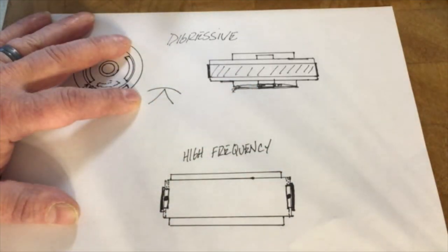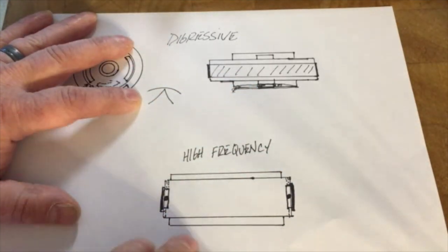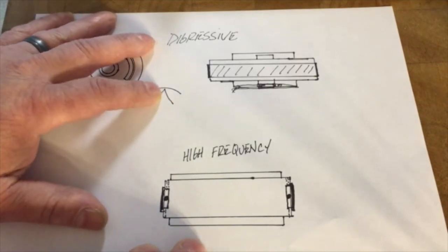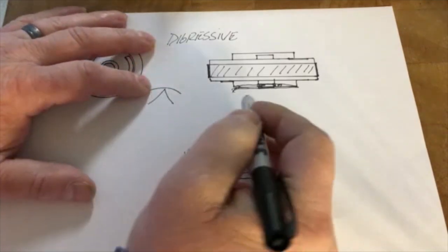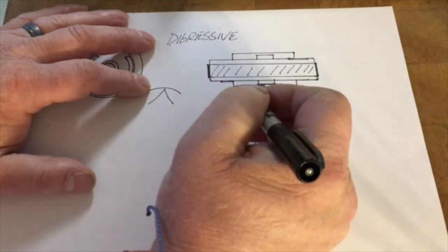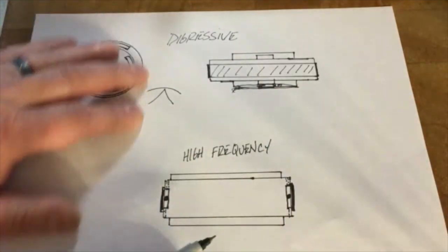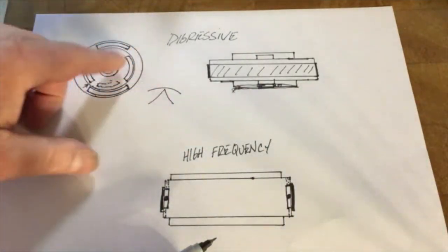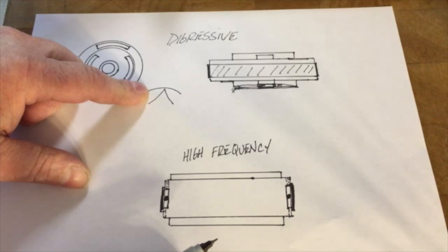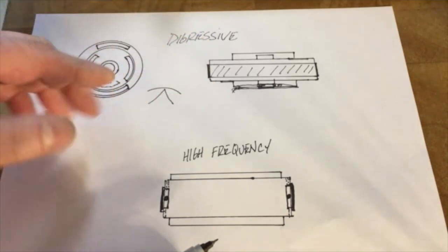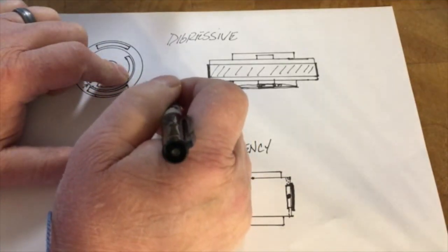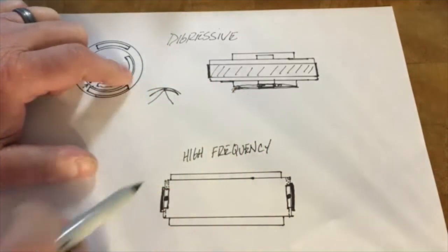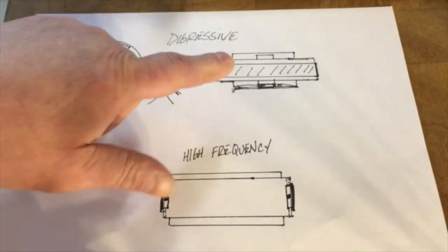Pointed ones probably are a little stiffer there. When they get kind of rounded out, they'll have a little bit of a control rate built into the compression and the rebound. I don't know, if it really has a lot of bleed, it will be way too sloppy, but you'd still want a little bit of control at the top and the bottom without putting bleed in there. I think there's something there.